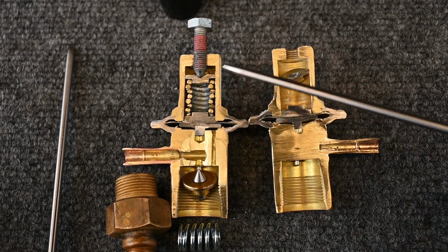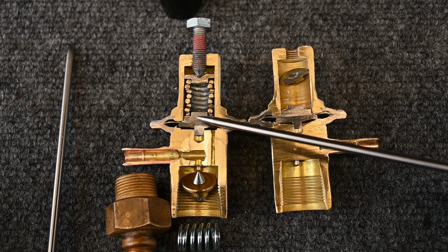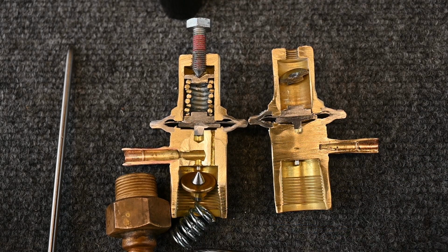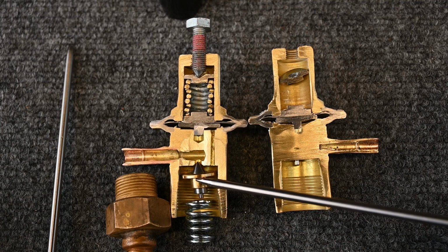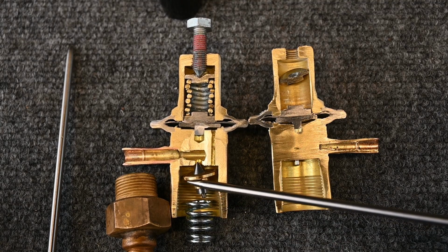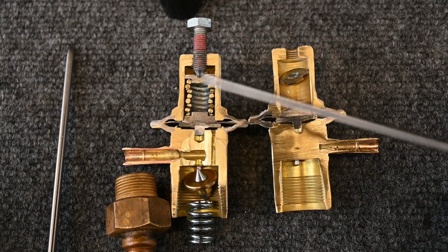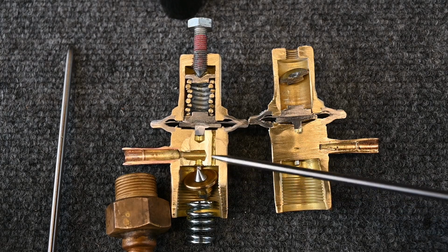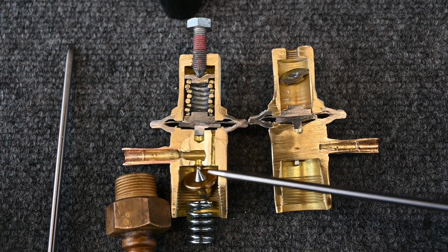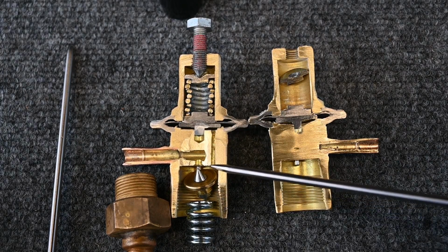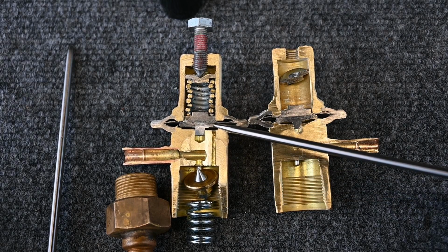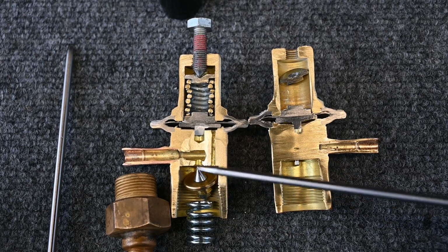So it's essentially, we have three pressures. We have our spring pressure pushing down on the plates against the pins, forcing the valve open. We have this spring pressure that's always pushing up against this pin, against this cone, the metering device, to close it off or to reduce the pressure. So these springs balance them out, pressure 1, pressure 2. And then third pressure is our actual refrigerant pressure. And that's what's essentially breaking the difference between the two springs. So the little bit of difference between this tube right here, the pressure in this tube, overcomes and changes it to where it maintains a constant pressure.